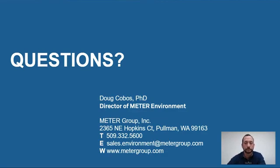Okay, next question. There are several questions in here similar to this. What are some of the basic sensors that are now available for water potential? Yeah, that's also a great question, and that's probably a water potential 201 or 301. But if you're talking about in the environment, the tensiometers are just brilliant sensors in the wet end. And then when you start getting toward the dry end, you generally are going to be using the vapor pressure methods like a dew point potentiometer or a thermocouple psychrometer.